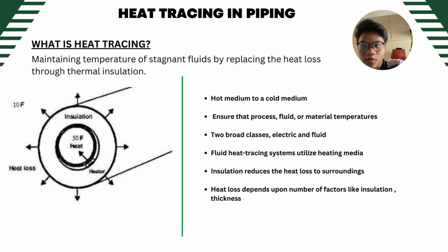And for the process of heat loss in insulated pipe, heat loss takes place from a pipe carrying a hotter or colder fluid than the ambient temperature. Also, insulation reduces the heat loss to the surroundings, and heat loss depends upon a number of factors like insulation thickness, ambient temperature, and also wind speed.